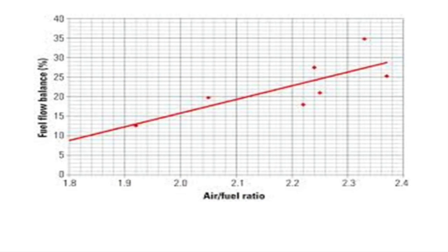Sometimes it doesn't actually have to be a mechanical problem in the pulverizer, but here's a case where some mine debris has been caught up in the classifier section of the pulverizer. This caused a big pipe imbalance issue and was actually the root cause of a big slag problem where we had the unbalanced oxygen because of unbalanced coal flow, and here's the root cause being a coal quality issue, because I'm going to call that trash in the coal. So most coal contracts don't allow for trash in the coal, and here's a case where it actually caused a slagging issue.